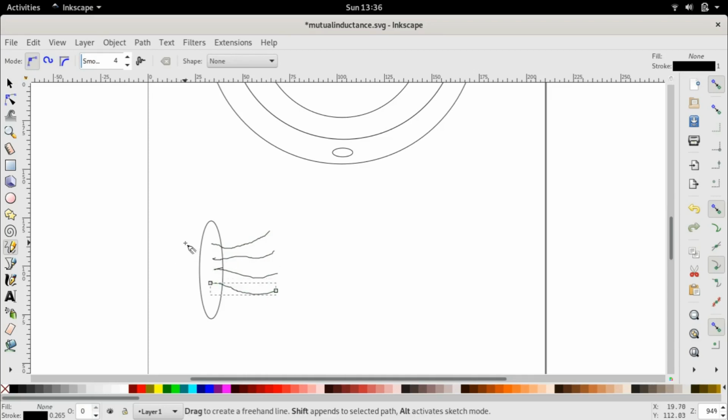And if we were to look at this coil from the other direction, that is from the left to the right, then the current would be flowing in the coil in the counterclockwise direction. And because it is flowing in the counterclockwise direction, that face of the coil, when we are looking from the left to the right, becomes the north pole. And therefore the flux will be leaving the coil, right? Always remember, flux flows out of the north pole and into the south pole. So this way, we can say that this is how the flux is produced. Of course, this flux will then come over here and complete.